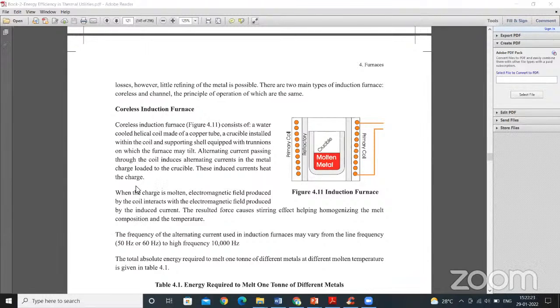And similarly, they have to prepare the pieces, the mold, in such a way that once the metal is ready, immediately they have to take it up. We have to tap all the metals and it should be poured. So preparation work to take the metal is very important. You have to start the preparation work minimum half an hour before, even sometimes 1 hour before the molten metal is taken out.